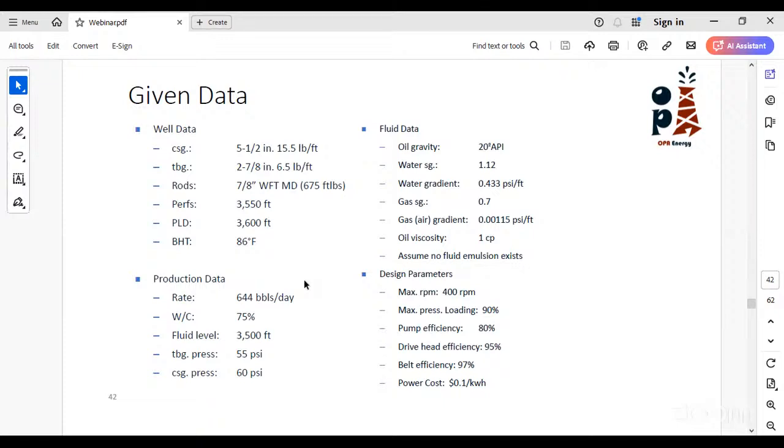So we will start designing this well, starting from the design of the displacement, or the pump that fits your displacement or flow rate capacity. This is the first thing. The second thing is to choose a pump that fits your net lift capacity, or the discharge pressure and the difference in pressure between the discharge and the intake pressure to fit this application.